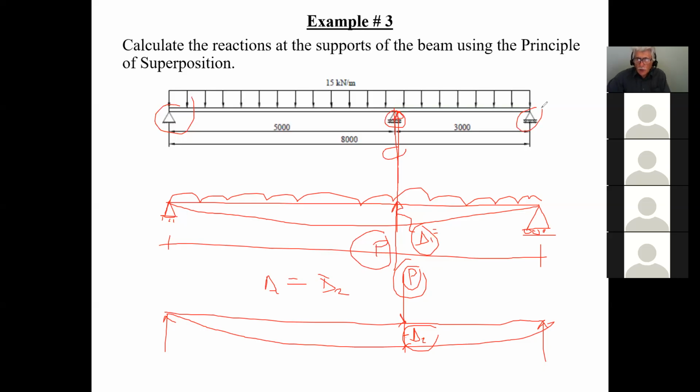So you see how you use the principle of superposition? By the deflection caused when I remove the support, if I can calculate a force that will bring that deflection back to its original position, then I know that force is going to be equivalent to what the reaction would be if that support is there. Isn't that convenient? I don't know about you guys, but when I saw this the first time, I thought the guy that thought about this was pretty smart in my books.